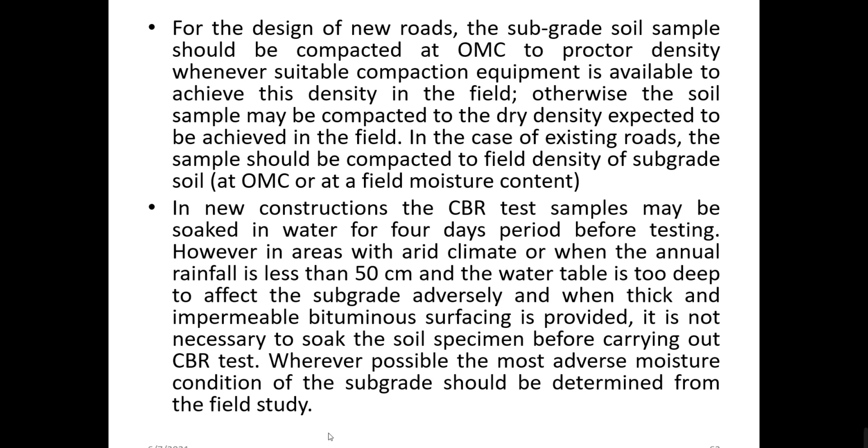If the annual rainfall is lesser than 50 centimeters, then it is not recommended to have the soaked CBR test of the soil sample. Or wherever the water table is too deep to affect the subgrade, then it is also not necessary to go for the soaked CBR. And again, if the bituminous surfacing provided is impermeable and very thick, then again we are not going to go for the soaked CBR, because if the thickness of the flexible pavement or bituminous surface increases, then water cannot penetrate into the pavement and reach the soil subgrade.